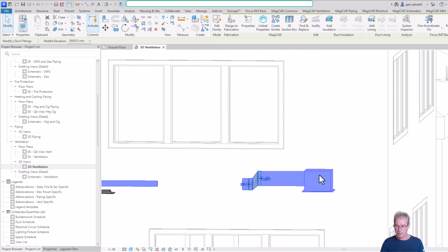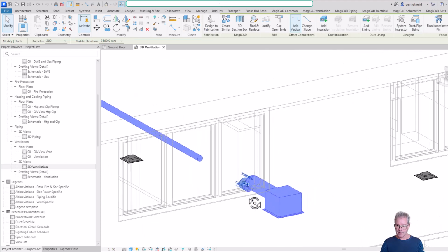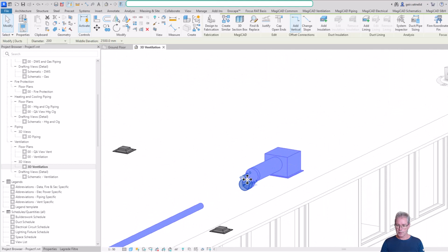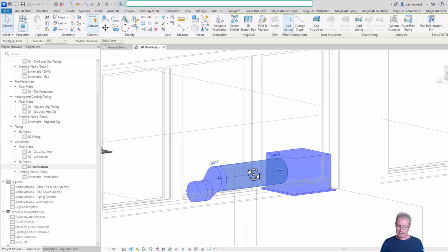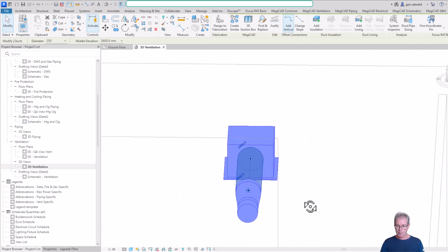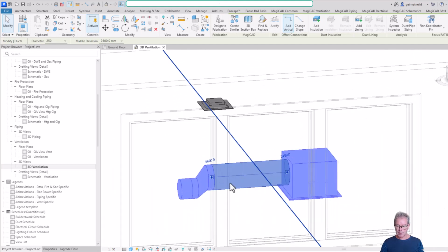and also we have an unnecessary bending here. That is because the height of this terminal is higher than the height we chose for the duct we have drawn. So if you want to have that in the correct position, check the elevation here. It is 2.4 meters and 2.6 meters.